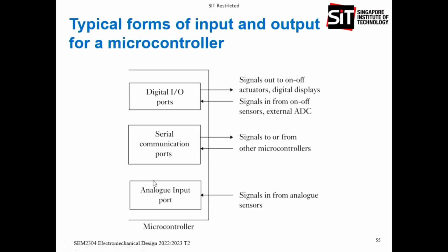Okay, so this is a typical form of I/O in a microcontroller. You can have a digital pin, all right? This digital pin allows you to either read a digital signal or write a digital signal, okay? This one refers to external DACs or ADCs, external meaning that it has already converted everything to digital form, so you can connect it to your digital I/O port. If you're talking about the internal one, then the analog signal goes in directly, okay?